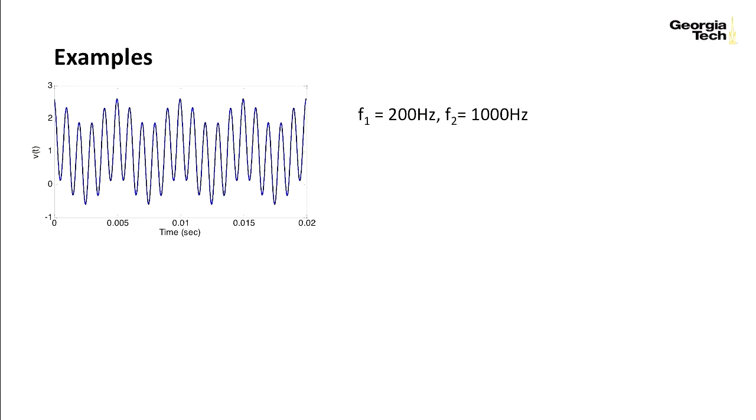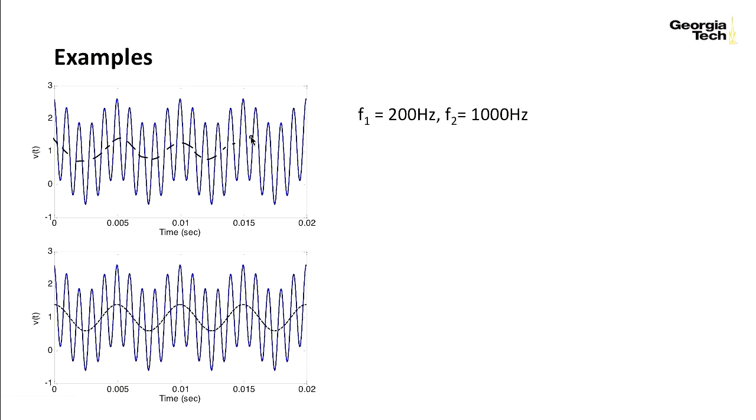Let's do another example very similar to that one. In this particular case, I do the same thing where I sketch in the low frequency average value of this. Or done more carefully, it looks like this. So the peak-to-peak amplitude here, I have to look at this from here to here, is 1. So peak to peak, that's what we always call P to P, or peak to peak is 1. So that means the amplitude is half of that, is 0.5.